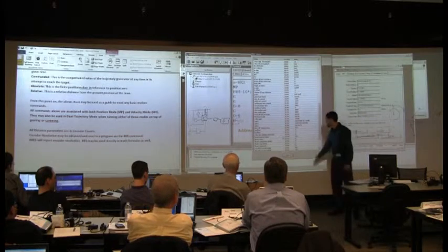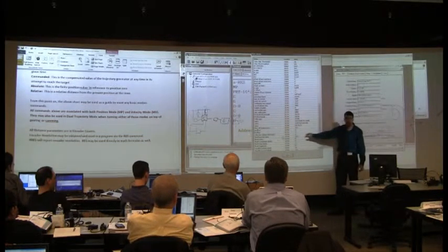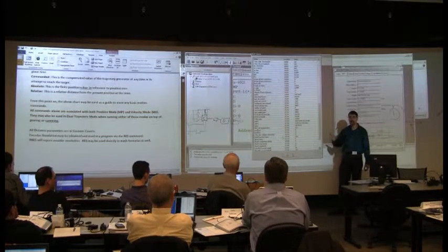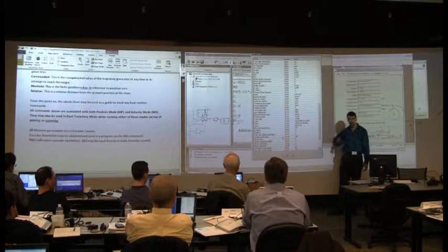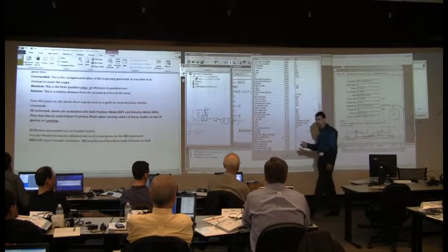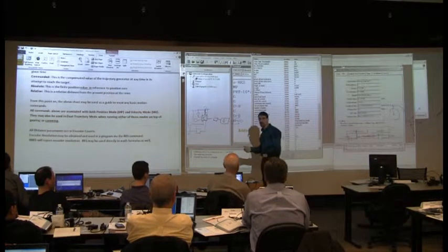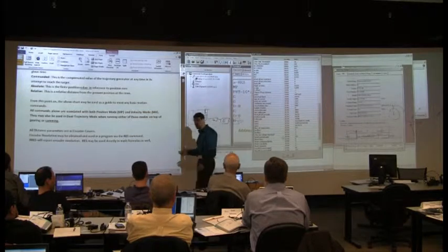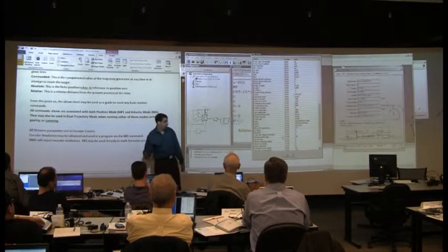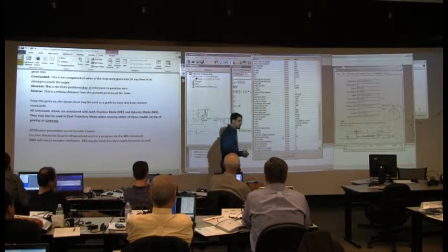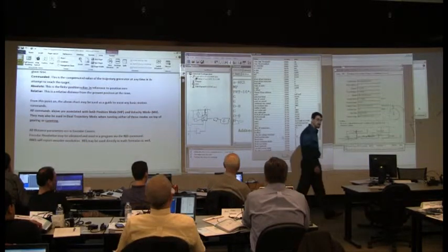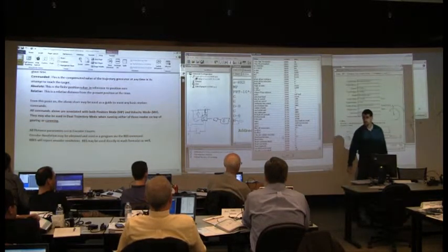What's going to happen is, if you get bus voltage way down there, PWM is going to increase out to the drive stage to make up for the lack of voltage. As a result, heat goes way up. Current consumption through the MOSFETs goes way up. And next thing you know, you're going to burn out the drive.